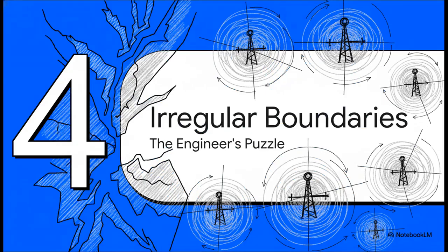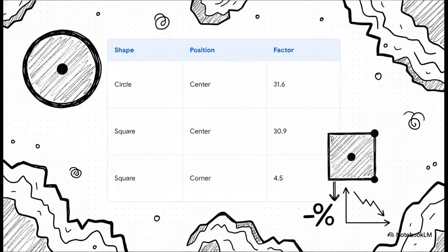Which leads us right into Section 4, Irregular Shapes and Boundaries, the engineer's puzzle. In textbooks, wells are always perfectly centered in these beautiful circular drainage areas. In reality, they're constrained by chaotic, messy geology. So, to account for this, engineers use Dietz shape factors. Notice how a well perfectly centered in a circle has a shape factor of 31.6. Centered in a square, it's 30.9, almost the same.